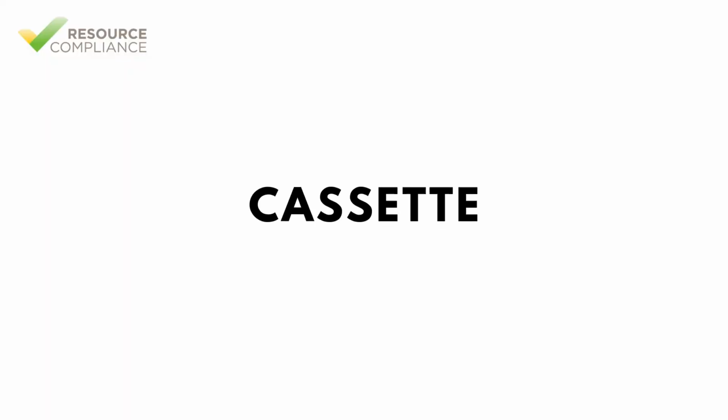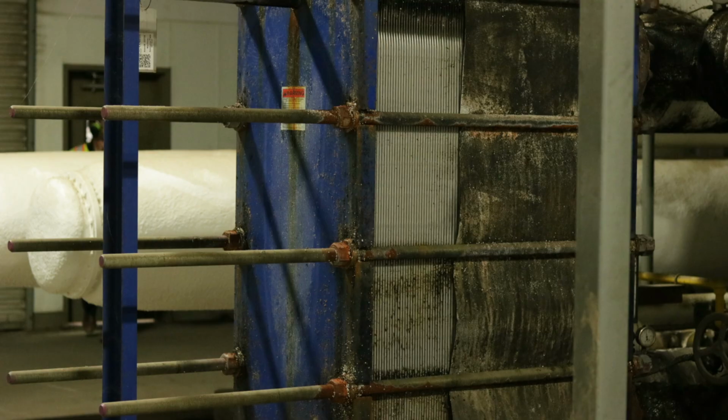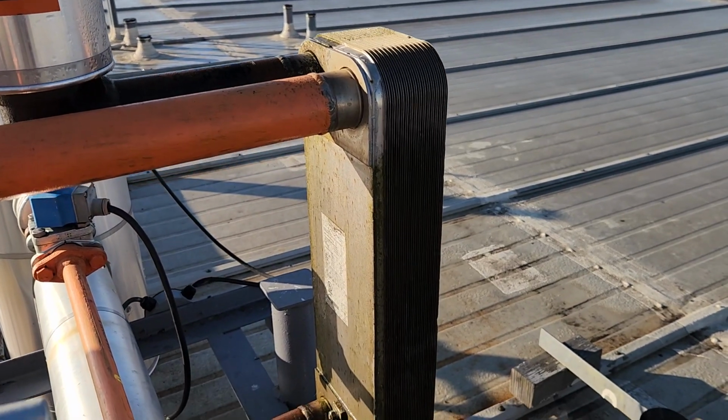A pair of plates is often called a cassette. The number of cassettes required will depend on the evaporator load. The cassettes are held together in a frame. The frame can be adjusted to add or remove plates if the refrigeration needs change. In a plate and frame heat exchanger, refrigerant enters the unit on one side of the plates and the fluid to be cooled on the other side.